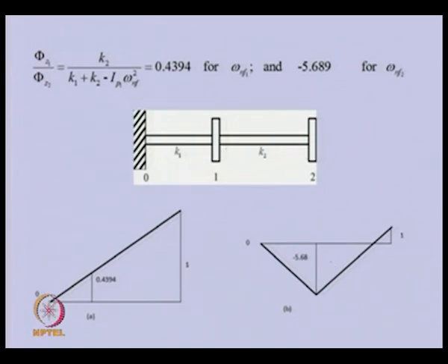So in the present lecture, we tried to use the transfer matrix method with various examples and various kinds of boundary conditions, to see how we can get the natural frequency and the mode shape. We will extend this method in the next lecture to other cases like the damped case and the reciprocating engine case, which we could not cover in this lecture.